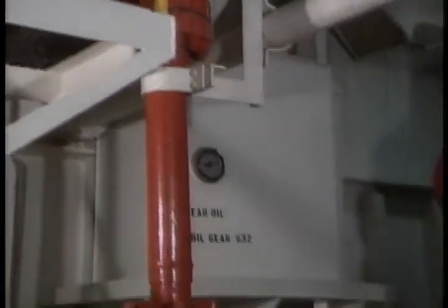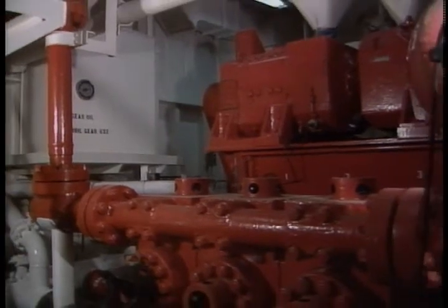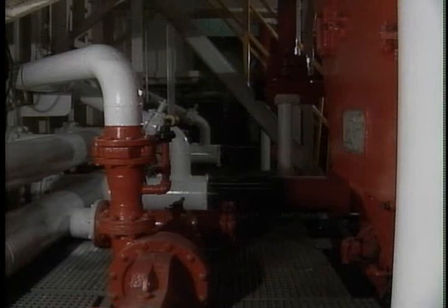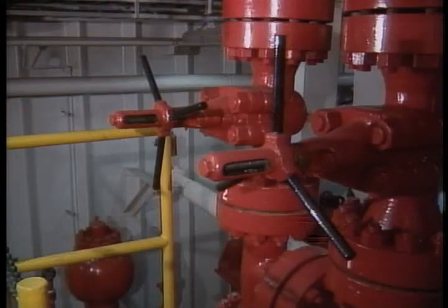There's one more area that you'll have to be familiar with as a derrick man in the mudroom. That is the system that transfers the liquid muds from tank to tank and to the mud pumps. Each system will be different on each of our rigs, but there are enough common things about them to allow us to talk about them and hopefully help you understand them. Let's take a close look at this maze of pipework so you can understand it a little better. Just keep in mind that these pipes and valves are here to allow you to feed fluids from any part of the system to any other part of the system.